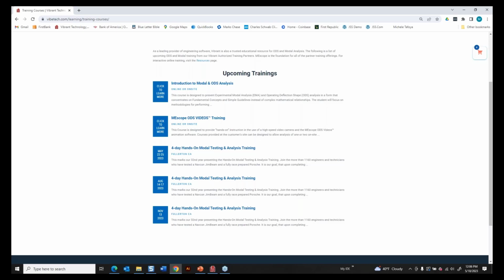Well, the Achilles heel of using a neural network is training it, because it's a model of your brain. And just like a child has to go through years of learning, you have to train the neural network with a lot of data, but you have to label the data. In other words, when you feed data in to train the network, you have to tell it, okay, here's some data for a stiffness change, or in the case of a machine, here's some data for misalignment or unbalance or soft foot. These are typical problems in rotating machinery in a plant.